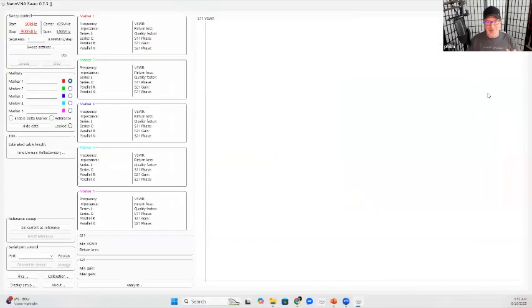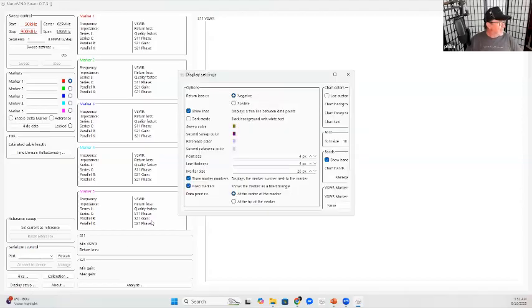So this is a live demo, everybody. This is a whole brand new install. NanoVNA Saver has run on my machine. The first thing I'm going to do is go to display setup down the bottom left here. It's already picked up my changes, as I have installed it before on this machine. You always want to show lines because we know a NanoVNA makes a number of discrete points, and you want lines so it connects them all.